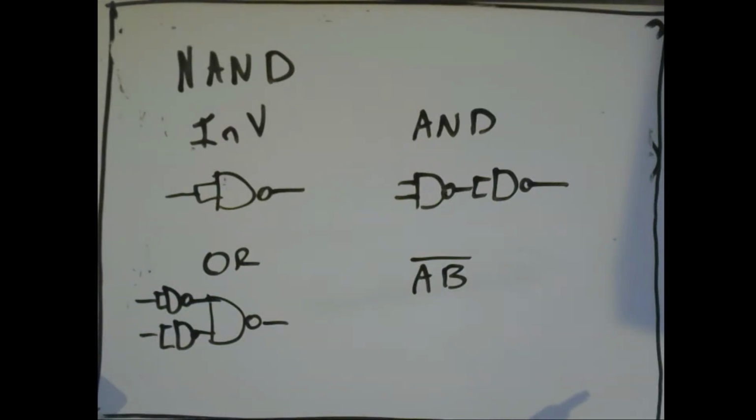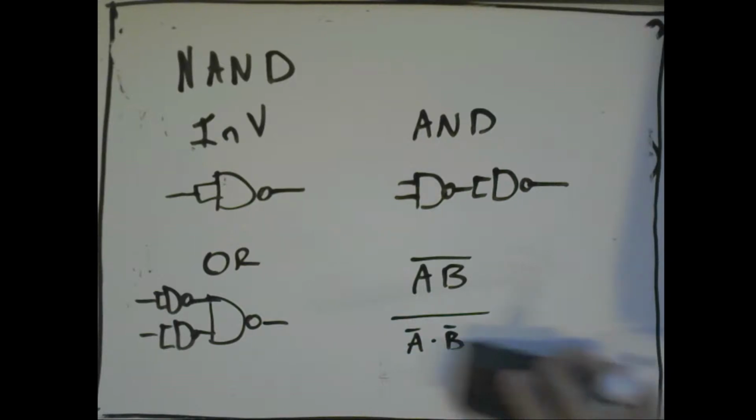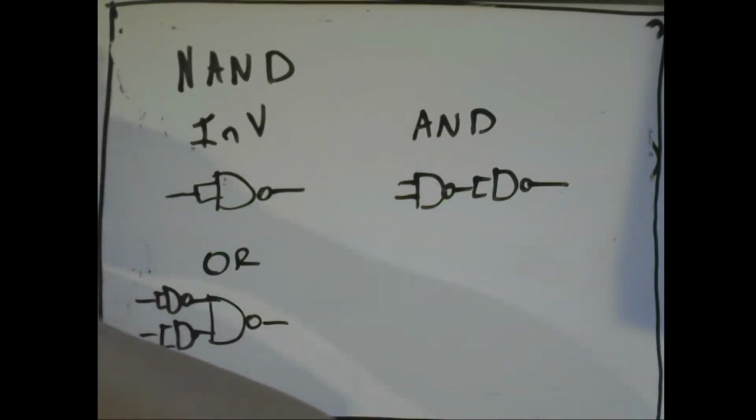When we do this, this is the same as writing this. It's like a NAND, but the inputs are inverted. If I apply De Morgan's law, I can combine the line and change the sign here. That's a double negate, so that's just A plus B. So that's why this OR gate works like this. These are the things you need in order to write any type of circuit using NAND logic.